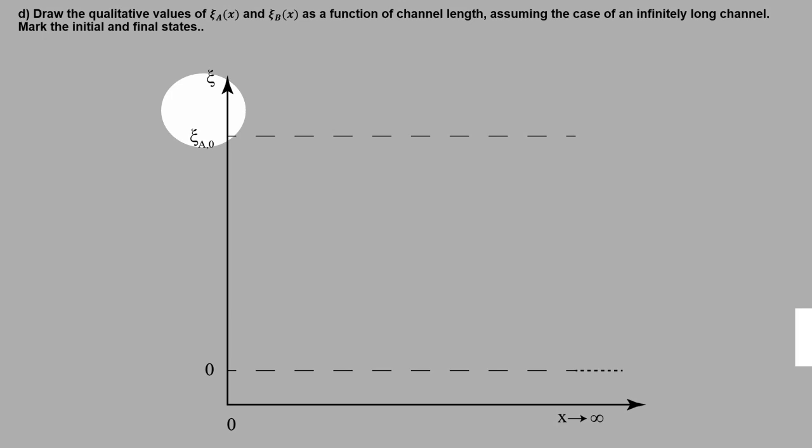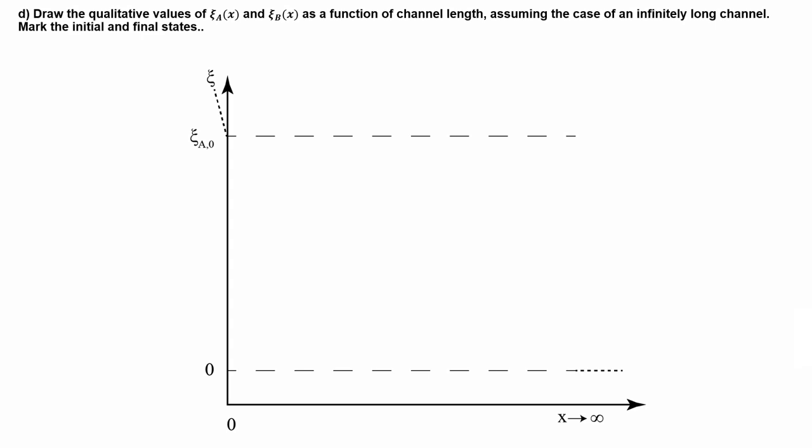At the inlet, it must be equal to the inlet mass fraction of component A, and the slope will be the steepest since here we have the highest conversion from A to B due to the most particles of A being present. So in between these 2 points, the slope of component A gradually has to decrease.